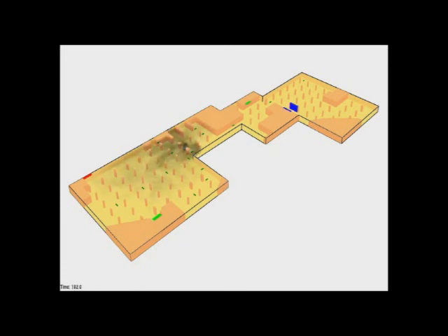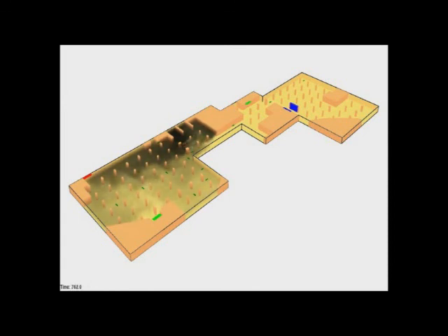We have to ensure that visibility is maintained in at least 60% to 70% of the area of the basement. Here you see this fresh air source is making sure that in this area visibility is decent. And there is a fire exit here, so people can run out from here with decent visibility.